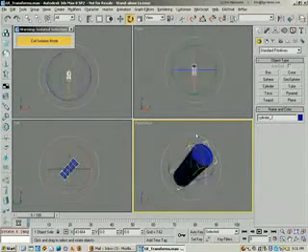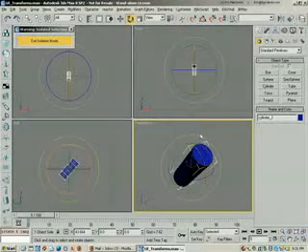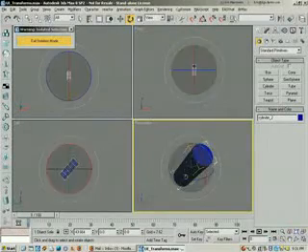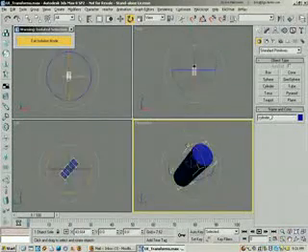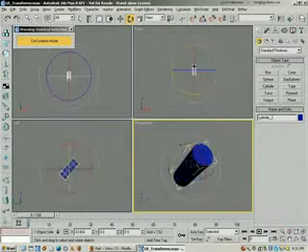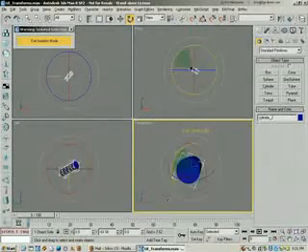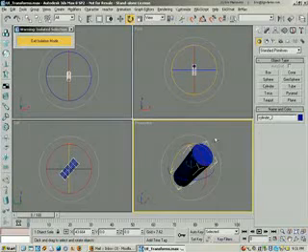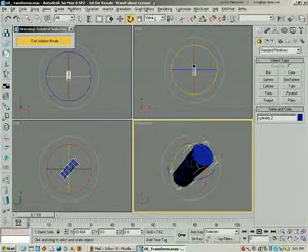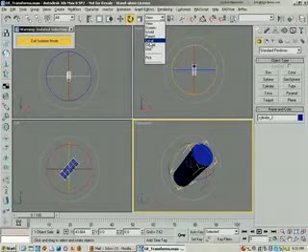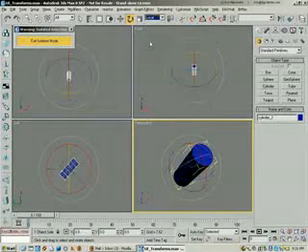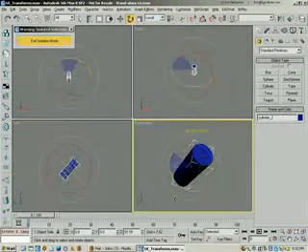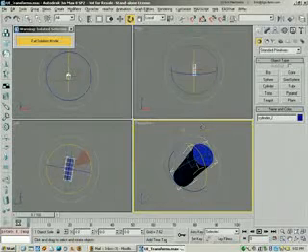You'll notice that our coordinate system didn't change at all. It's still upright because it's currently still aligned to the world. And as I rotate this along different axes, particularly the y-axis or the green, you notice it doesn't exactly rotate how I'd expect. So what we can do is change our coordinate system to that of the object, which is local. Now if you watch our coordinate system, you see that it's now aligned with our object. And we can now rotate it in a more intuitive way.